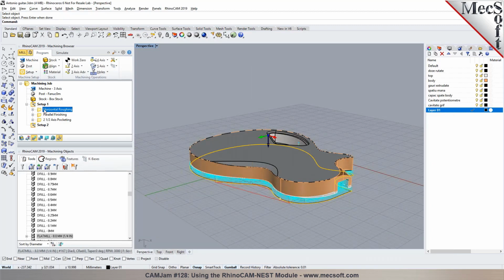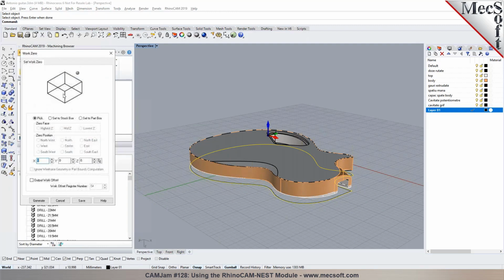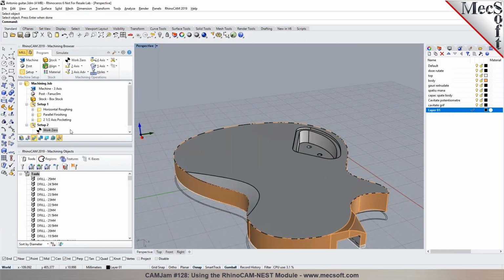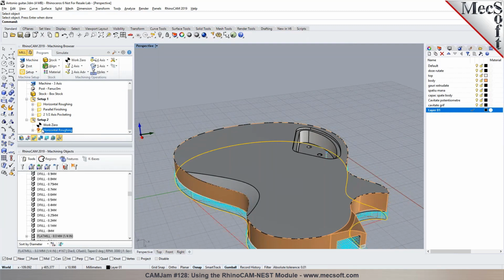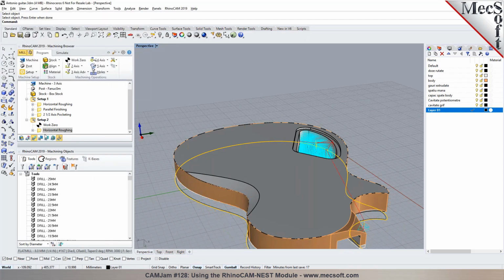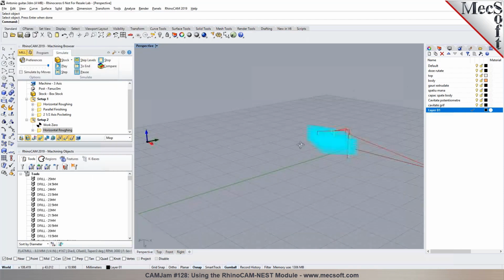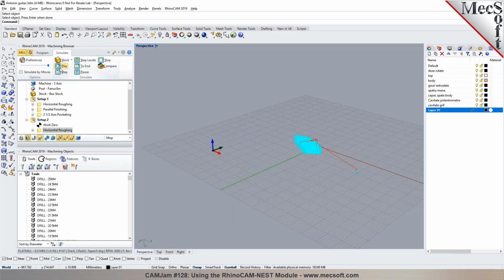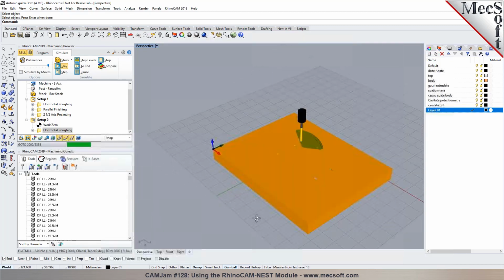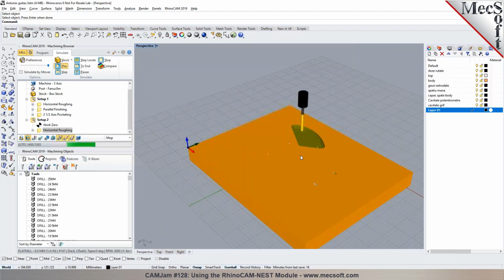So I'm going to select the same area right in here. I will put the 0 to the top and the lower left corner like we did before. And we can now create a roughing path, generate the toolpath. So we are now programming a roughing toolpath for the other side. So now the roughing toolpath has been generated. You will be able to simulate from multiple sides. With the Pro, you can see the roughing from the first side and the simulation from the other sides.